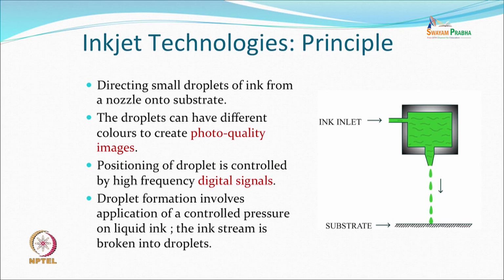So, all that information has to be sent through various transducers to the jetting area and the nozzle, and then there has to be a mechanism of continuous feeding, breaking the jet into droplets, and then we hope that there is an affinity to the substrate and there is a process post printing which can ensure that there is a fixation of whatever drops that have come.